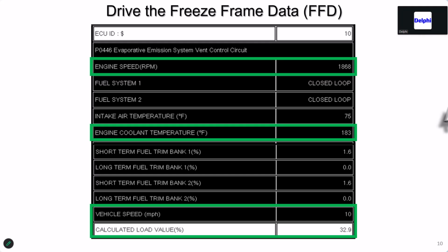Okay, the other place you get some good information is your freeze frame. If the cars come in with a MIL on, save that freeze frame. My experience has been about 98% of the time the freeze frame shows the enable criteria and the conditions under which it's set. To get out of trouble, those same conditions are still used, but in a couple of cases, like Nissan mass airflow sensors, if you set them, they have a different criteria to get out of them.